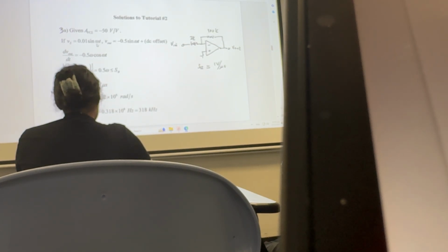You already exceed the slew rate limit, right? From sine wave, although the sine wave responds, you already exceed the slew rate limit. Let's say 1 meg, right? Let's say you input frequency equal to 1 meg, you already exceed it. Right? So what happened to the waveform? Can you tell me? It will be like that.